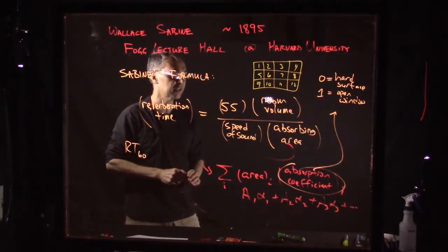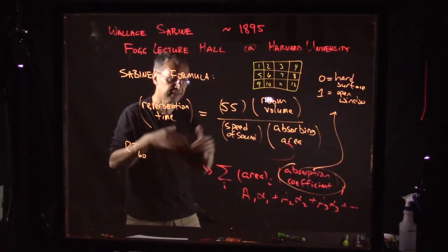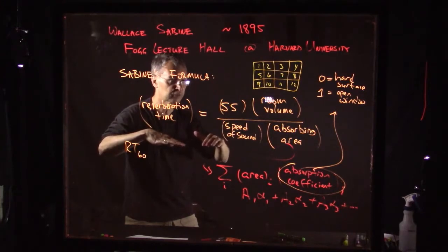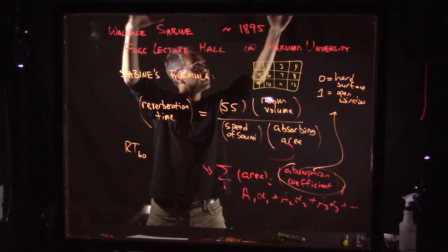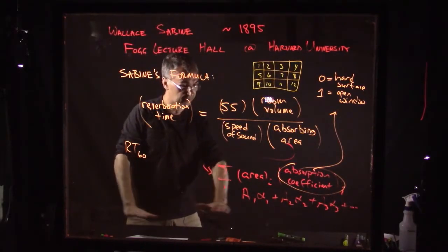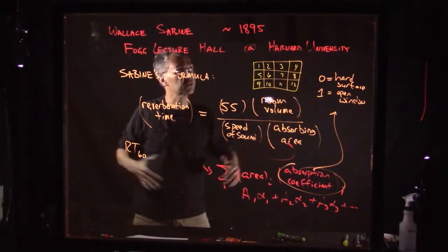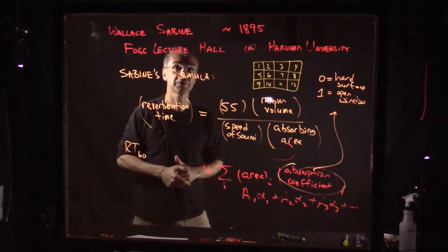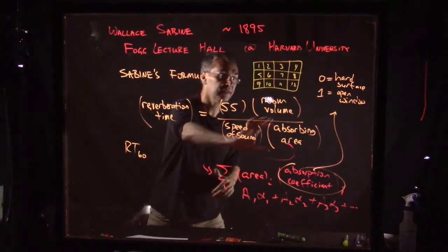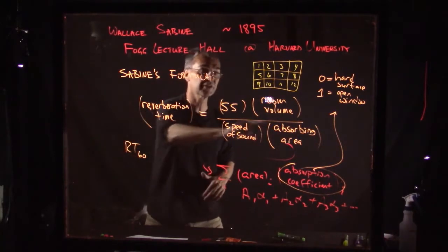You can see this sometimes in loud restaurants if they want to improve the speech intelligibility, if they want to get it so that you can talk to the person across the table from you without too much background noise. They'll put absorptive tiles on the ceilings. Carpeting isn't always great in restaurants, but sometimes you can use carpeting, or you can put some kind of soft material on the walls. The easiest place to put it is the ceiling, of course, because aesthetically and functionally it works best on the ceiling. But in any case, you cover as much of the surface area of the room as is feasible with a really good absorber, and you can cut the reverberation time down.